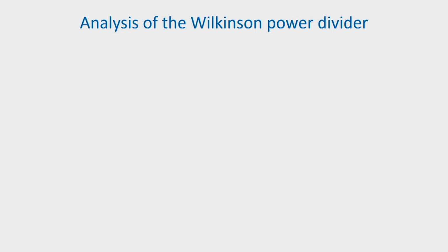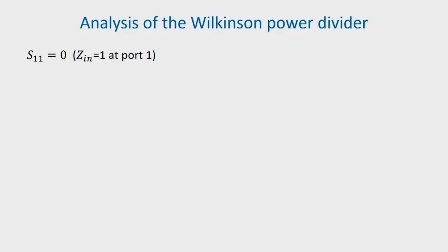So, once we have found out Zin equal to 1, that means S11 will be 0. So, we can now summarize, since Zin is equal to 1 at port 1, we have S11 equal to 0.